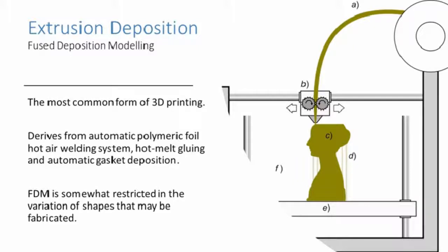Plastic is the most common material for such printing. Various polymers may be used, including polycarbonate, polylactic acid, high-density polyethylene, and high-impact polystyrene. In general, the polymer is in the form of a filament fabricated from virgin resins. There are multiple projects in the open source community aimed at processing post-consumer plastic waste into filaments. These involve using machines to shred and extrude the plastic material into filaments. Additionally, fluoropolymers such as PTFE tubing are used in the process due to their ability to withstand high temperatures.